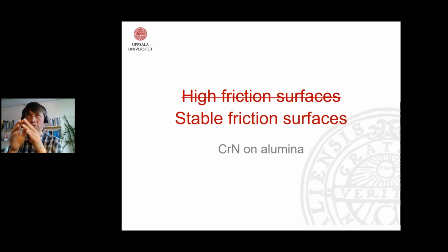So depending on the environment, the friction between these 2 surfaces can vary a lot. And it's especially difficult if alumina parts should be used in vacuum, because what can happen then is that the two surfaces are really in contact. There is no adsorbed layer on these surfaces that would separate the two components, and these surfaces can in a way weld or stick together, and this limits terribly the lifetime of the whole system.